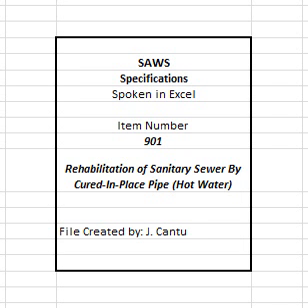2. Resin. A. The resin system shall be a corrosion-resistant polyester, vinyl ester, or epoxy and catalyst system. B. When properly cured, the tube composite meets the requirements of ASTM F1216, ASTM F1743, and ASTM F2019, the physical properties herein, and those that are to be utilized in the design of the CIPP for this project. C. The resin shall produce CIPP that will comply with the structural and chemical resistance requirements of this specification.